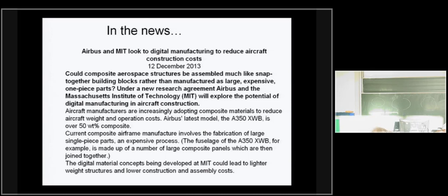Okay, that's very good. I would call it risk related. This is a big fuselage, even if it's a barrel, so the length perpendicular to the page is not very big. This is huge. If something goes wrong during all these steps that were mentioned that I have to go through, and I either don't notice or it's too late, then I waste millions of euros in labor hours, parts, materials, and so on. The risk associated with this is very, very large. Not to mention what I skipped, of course, that creating a mandrel of this size and making sure that it gives you the right geometry with the proper heat-up rate during curing can be quite challenging. So this is not the way to go.